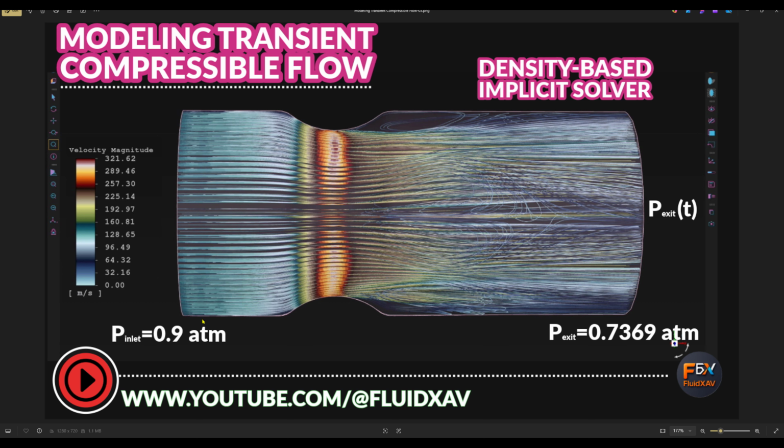In this lesson, we will work on modeling transient compressible flow through a nozzle using ANSYS Fluent. The nozzle has a sinusoidal contour with a 20% reduction, and we begin by running a steady-state density-based solution to generate the initial conditions for the transient simulation.